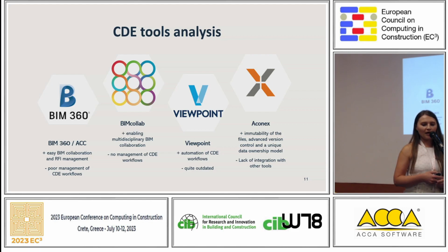Another tool was BIM Collab, which is kind of similar to BIM 360. It also provides very good level of BIM collaboration, but again, it doesn't provide the management of the CDE workflow. And the tools that are providing those functions are, for example, Viewpoint for projects or Aconex. So they are very advanced, and they even make it possible to automatize the approval and sign-off processes. Additionally, Aconex also provide immutable record of transactions and very advanced versioning